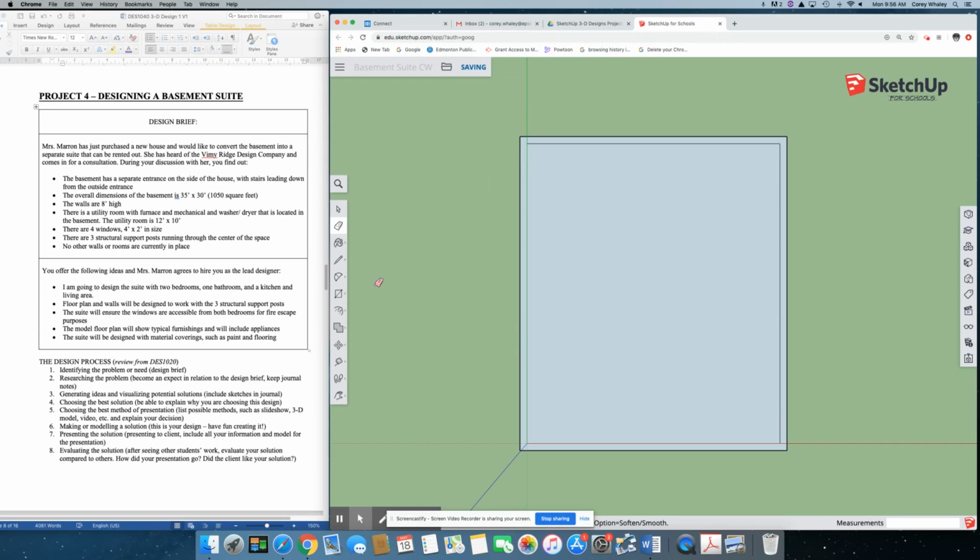So I'm going to just create that outside door space for now. I'll grab my rectangle tool, and you can just decide where the door is going to be. I'll say maybe we start right there, and the door is, I don't know, 3 feet wide. We're going to drag that out, and I guess we can eyeball it. That's about 3 foot 4 inches. Let's go 3 foot 6. Actually, we'll make it exact. Let's go 3 feet 6 inches exactly, and then click enter, and there we go. So now we've got that door that's 3 foot 6.